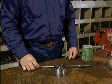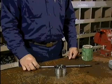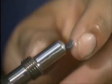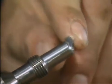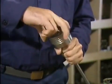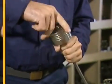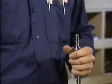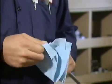If either the stem or the disc is replaced or has any flat spots, you must lap the two parts together. This lapping process is called grinding in. Apply a thin layer of abrasive compound to the end of the stem and use a rotary motion to grind the stem into the disc. The grinding in continues until smooth, even contact is obtained between the stem and the disc.